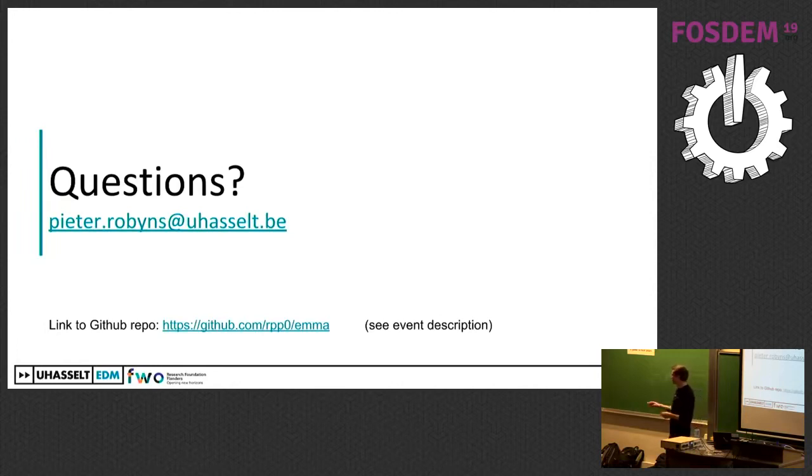Have you tried doing this attack multiple times for different kinds of keys? Have I tried it on multiple keys? Yes, of course. Yeah, it works. The training happens on random keys, so the test key that I used here is a key that I never observed. You train on the random keys and then you evaluate. Yeah. So sometimes if your alignment fails or if you have a very noisy signal, it could be that you require more traces, for example. So adding noise requires that you take more traces in your test set.